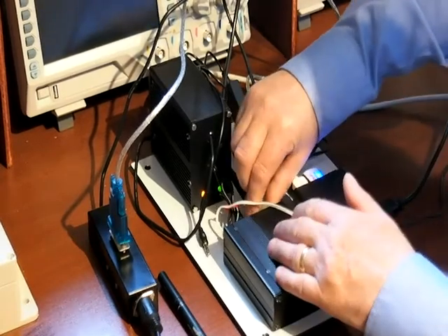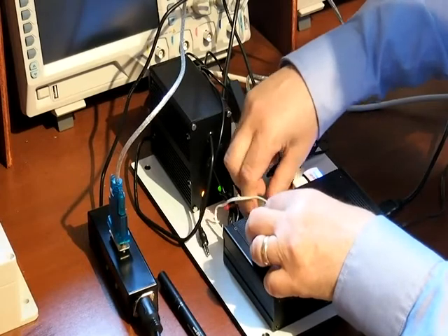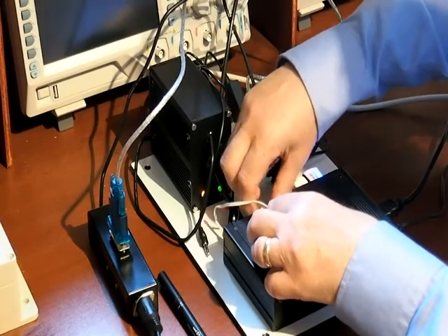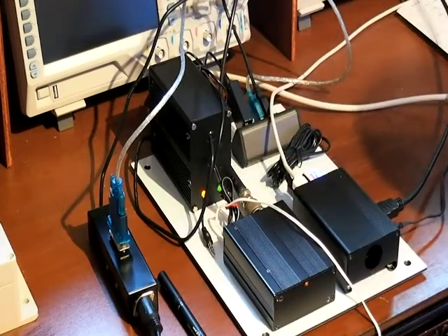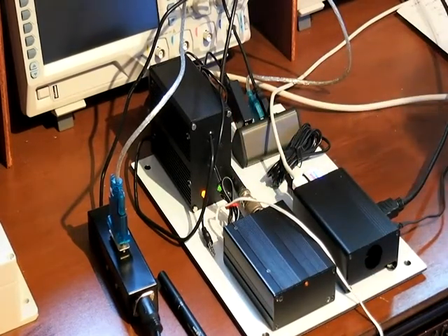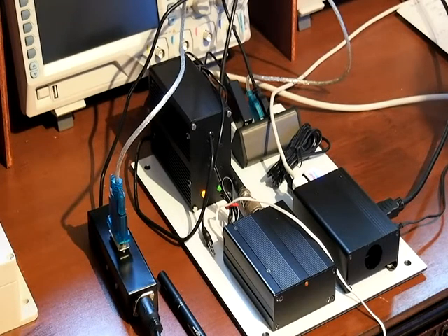We can then unscrew the antenna. There'll be some crackles as you do this. And then remove the antenna plug. The noise should go down substantially, and all I'm left with is a low buzz at harmonics of the AC power frequency. That's fine. All is well with the Whisper receiver.